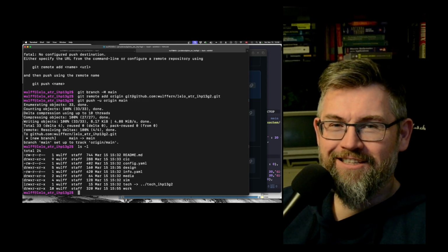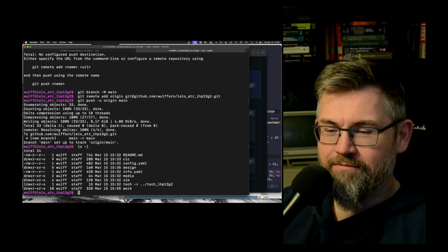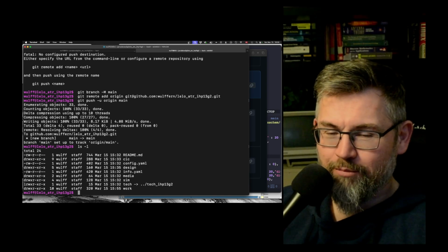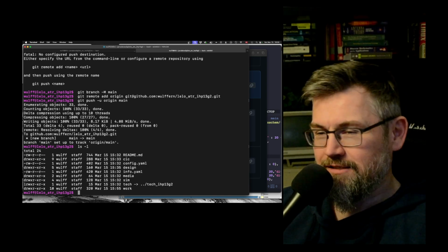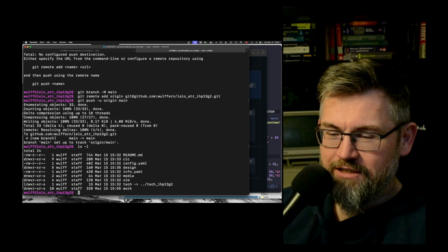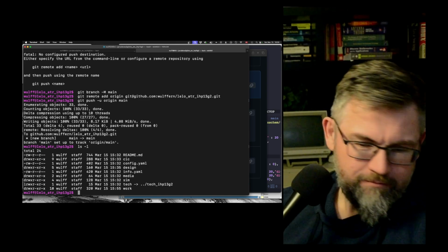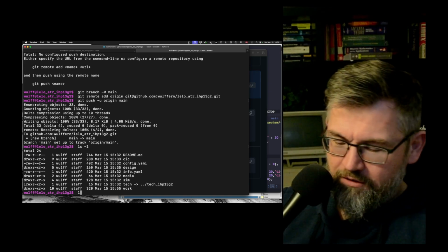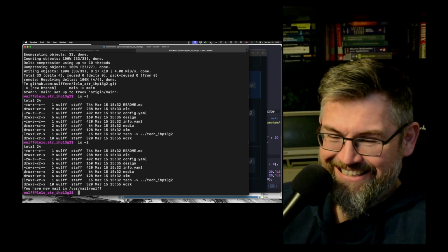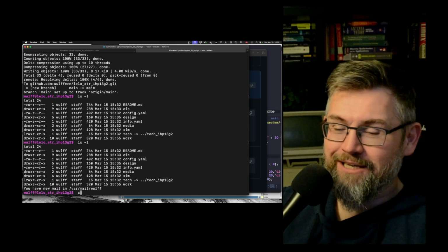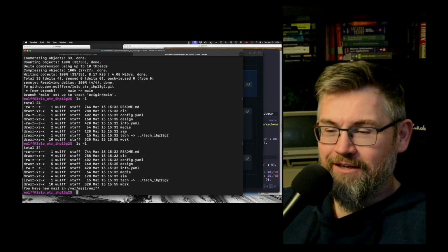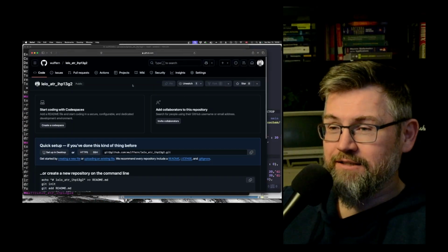And I need this open Verilog compiler in order to compile the models. And yes, I can run the simulation in Docker, but that's going to be slow long term, I think. So I just haven't set it up yet. But it's transistors. Well, I do need to simulate them to get the GMIDs and things like that out from them.